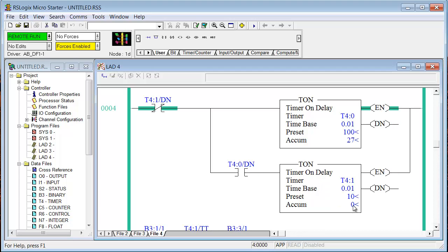That's why we didn't see anything changing when we were looking at the data monitor. It actually is changing. You can see that. Every once in a while it flashes a 6, 7, 8, 9, something in that neighborhood. We did not see that number in the data monitor for a real simple reason. The update time of the screen and the application is too slow to catch anything that quick, whereas we're right online with the processor here.